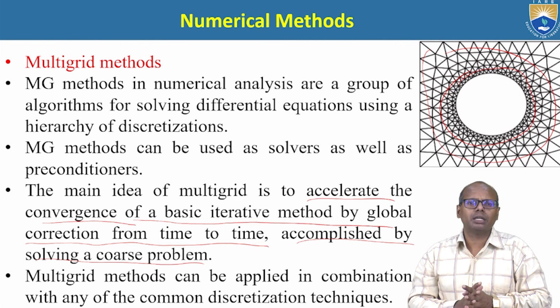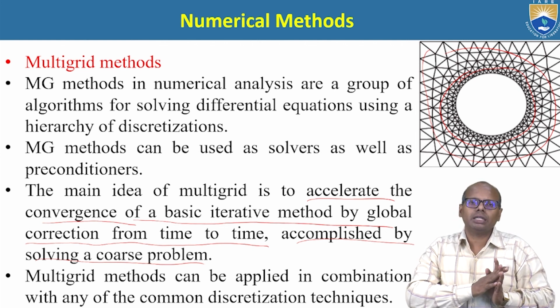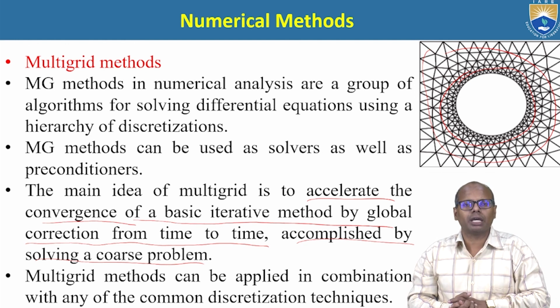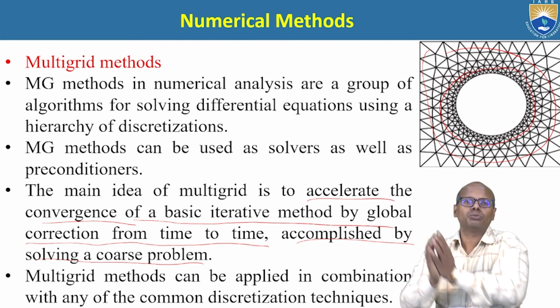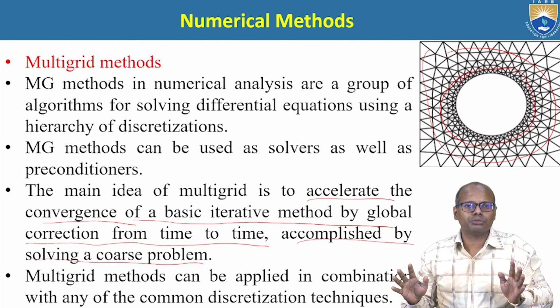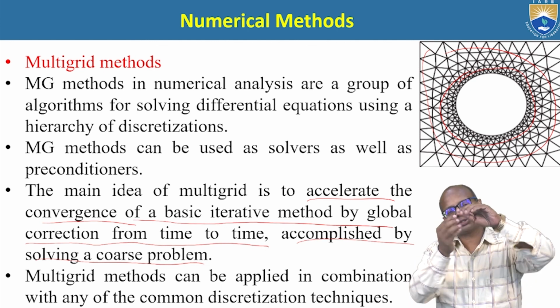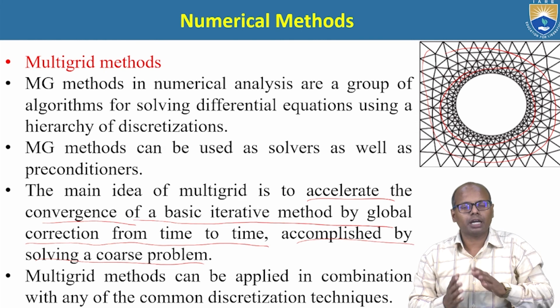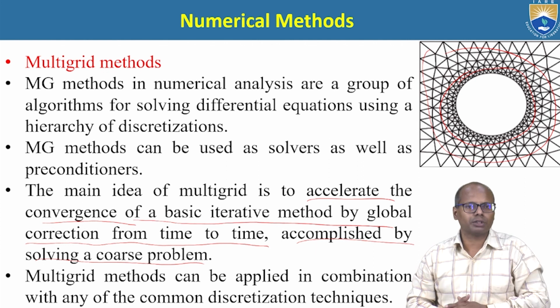FVM, the finite volume method, is easily applicable to CFD problems. All the commercial softwares that are available in the market are based on the finite volume method. So what is the finite volume method? We are dividing the domain into finite volumes. Finite volume means it is three-dimensional, so all flow problems are three-dimensional. Now if I have a two-dimensional problem, I will extrude it to some height, make the two-dimensional problem into a three-dimensional problem, and then solve using the finite volume method. Using this technique, all the commercial softwares are designed.